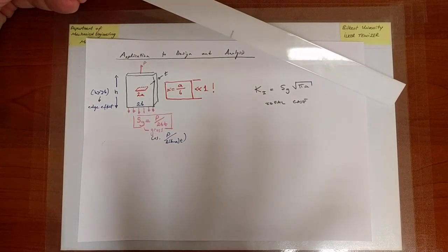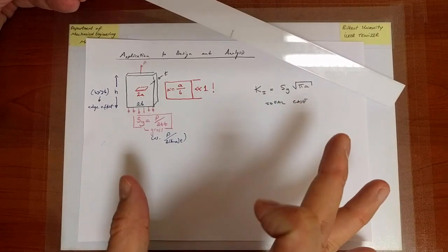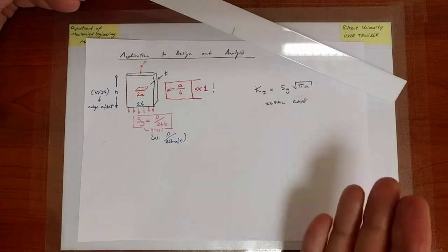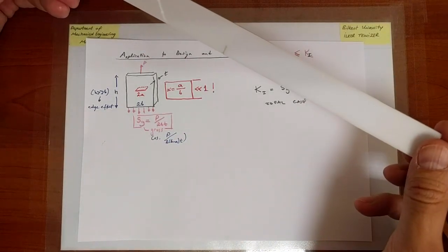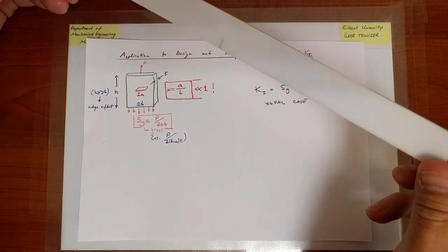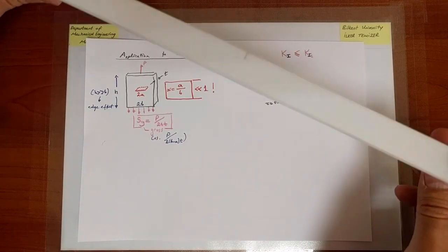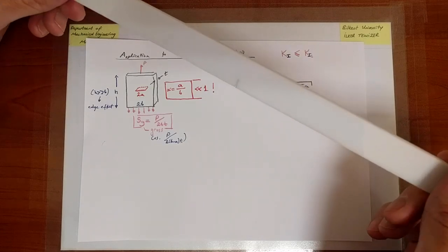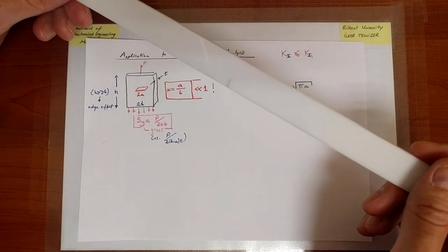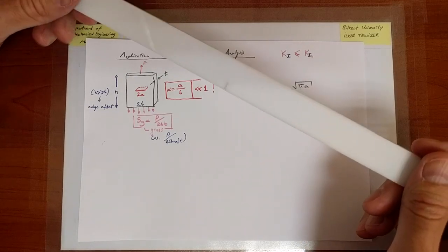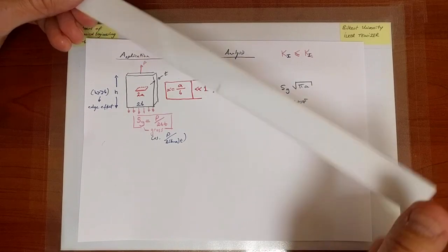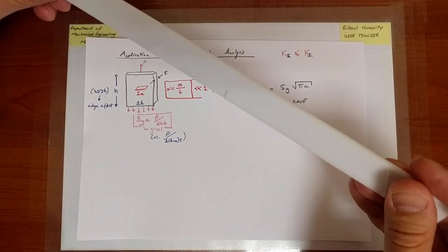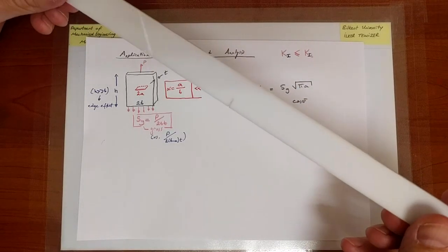The ideal case is still very important, because that is the prototypical case from which we first showed analytically the appearance of K1 in the expressions for the stress fields, how they vary with position away from the crack tip. But it is a very limited case. Plus, the geometry doesn't necessarily need to be in the form of a plate. It can be, let's say, a cylindrical rod, and there can be a fractured surface on a portion of it, a crack that is not necessarily of that geometry, etc., etc. Those are the types of generalizations that we would like to address a little bit.